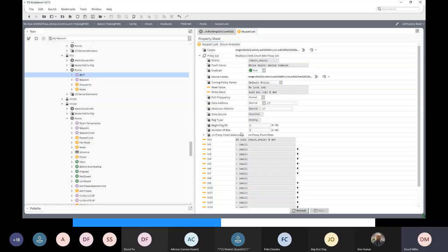Okay, so if you're mapping in a power meter, a good thing to concentrate on is the register for the line to neutral voltage. So if you map that in and you get the number 240, you know you've probably got it correct. Or if you got 238, it's probably correct. Or 245. But if it's 2040 or 2400, then you know you have to divide by 10 and so on.